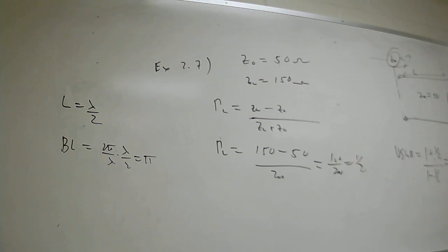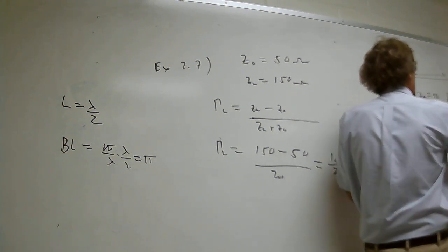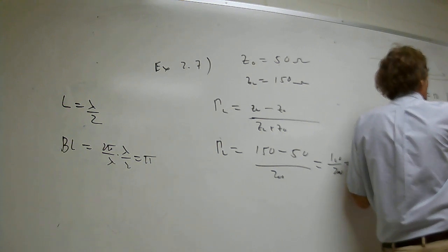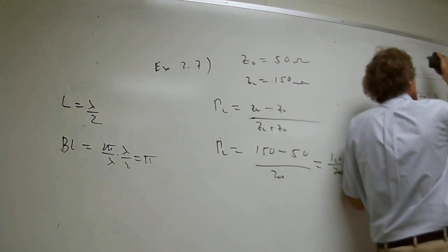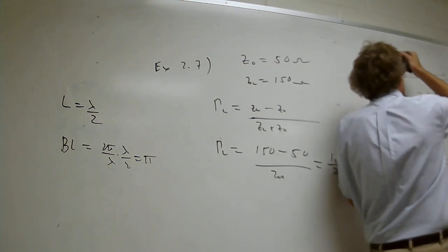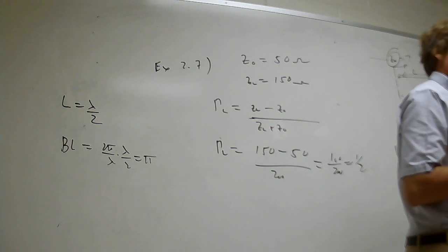This is characteristic and always true with transmission lines. Every half wavelength, everything repeats itself. If you graph the magnitude of V of Z versus Z, every half wavelength it repeats itself. It's a very important property.